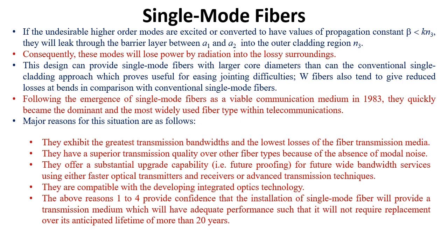They offer substantial upgrade capabilities, that is, future proofing for future wide bandwidth services using either faster optical transmitters and receivers or advanced transmission techniques. They are compatible with the developing integrated optics technology. These reasons provide confidence that the installation of single mode fiber will provide a transmission medium which will have adequate performance such that it will not require replacement over an anticipated lifetime of more than 20 years.